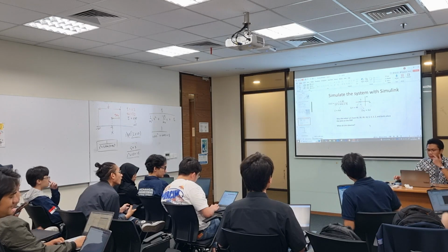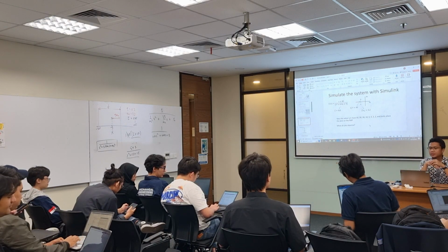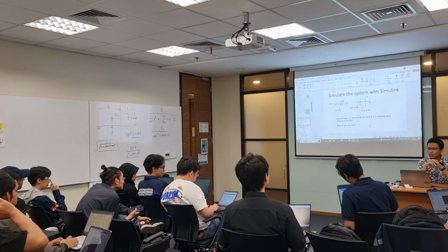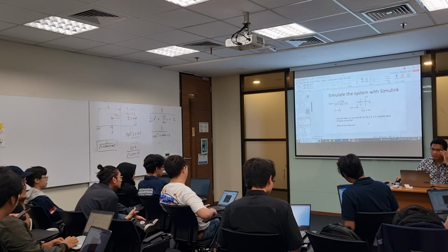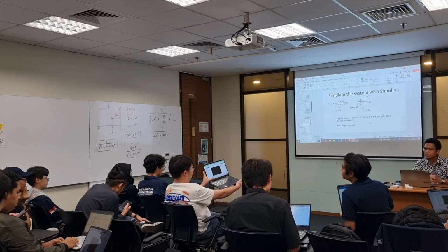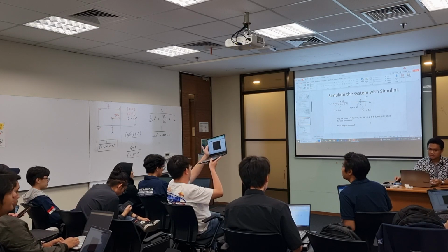So when you keep moving your extra zero closer to the origin, you can see a big overshoot. Okay, so if extra zero, if you're not careful, it can make your system to be more oscillatory.